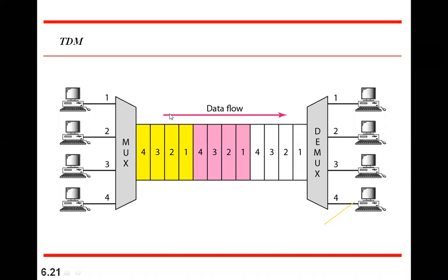Because the entire bandwidth is available, he can transmit at a higher data rate. Again, taking the same example, assume that the total bandwidth is 30 megahertz. All 30 megahertz is available for one slot duration to the first user.